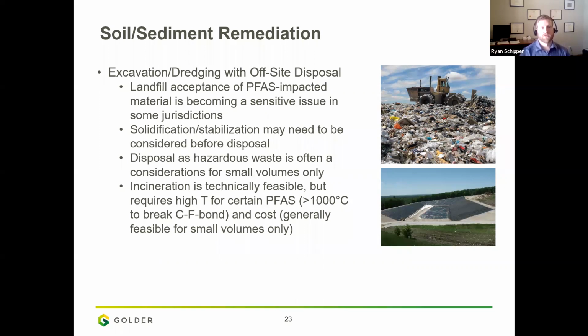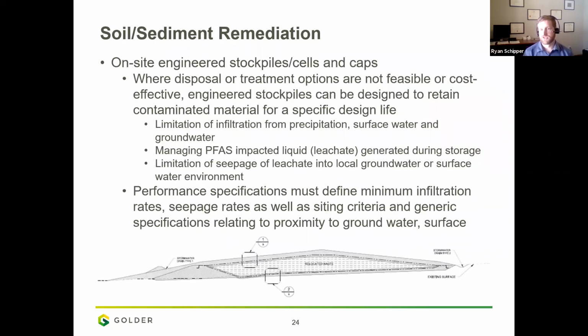Another soil and sediment remediation approach, on-site engineered stockpiles or cells and caps, is a very common management philosophy. We're trying to limit the infiltration of precipitation, surface water and groundwater, and leave the material in place. Obviously, this will still generally generate a PFAS-impacted leachate in many cases that could need to be managed for some time. So we're still generating some residuals if we're putting it in on-site cells.